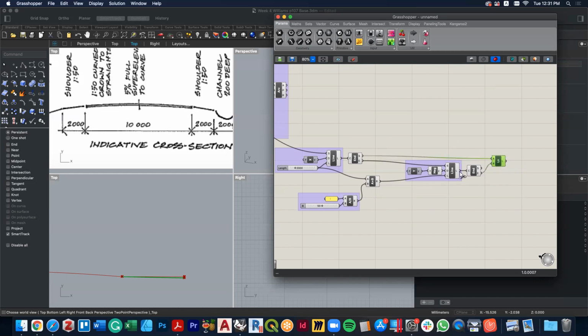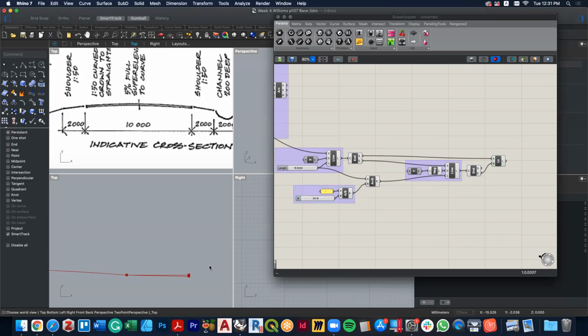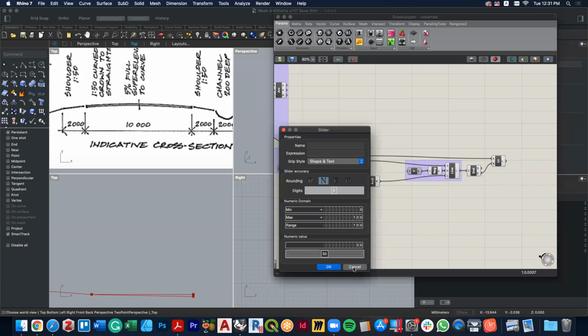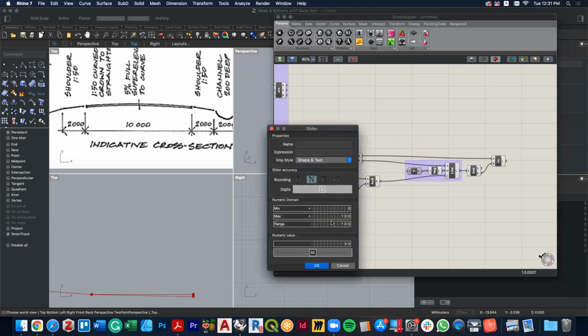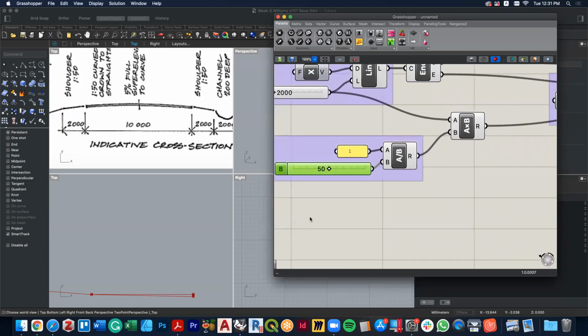And you'll see how now I have that second line. So obviously, it's obvious to say this, but if I wanted to make that 1:1:2, say I wanted to make that 1:20, I could do that, and you'll see how it shifts around. So that's just to demonstrate the fact that doing it like this is more laborious, but ultimately, if we later on wanted to change this road profile around, we can. That's the whole reason we use Grasshopper.